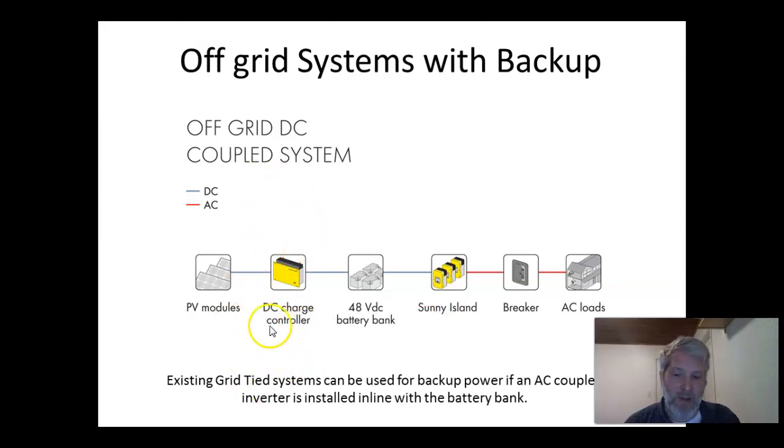The DC charge controller here is going to run off of the input voltage here, and it's also going to have an input voltage to control what it's charging on the side. You need to make sure that you match your DC charge controller to what your batteries are. Don't get a lead acid battery charge controller for a lithium ion system, because it could cause them to catch on fire, which would be really bad. So we do have a couple of pieces here that we have to work with.